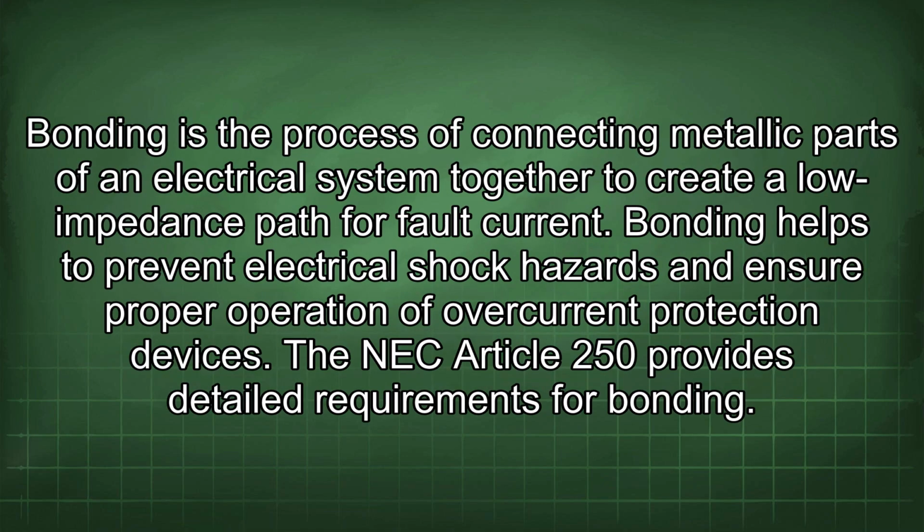Bonding is the process of connecting metallic parts of an electrical system together to create a low impedance path for fault current. Bonding helps to prevent electrical shock hazards and ensure proper operation of overcurrent protection devices. The NEC Article 250 provides detailed requirements for bonding.